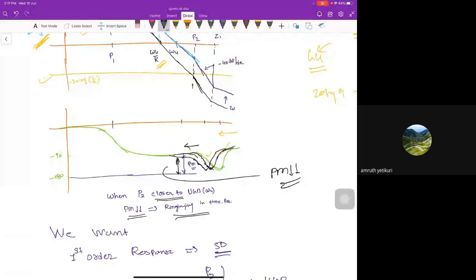We have already seen that adding a delay in the closed loop path means there are poles and zeros in the closed loop path. That will add phase lag in the closed loop path, and that results in different values of the phase margin. That's the link I want to create in your mind: the phase margin, ringing in the step response, and pole locations.